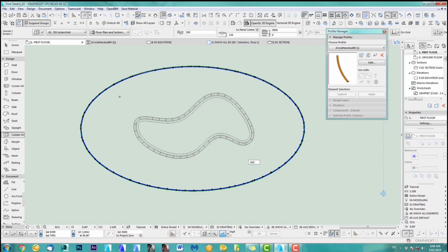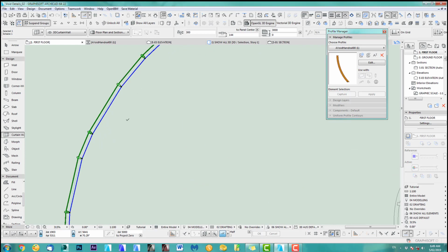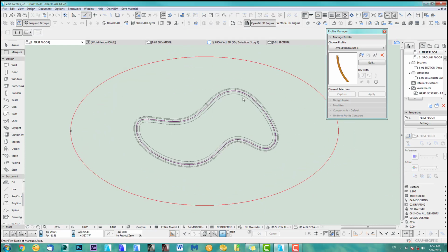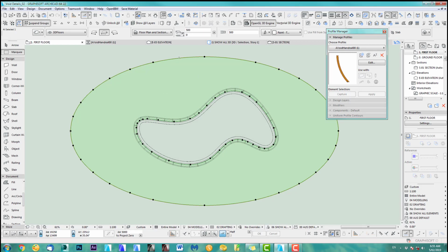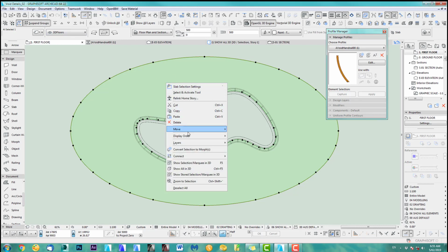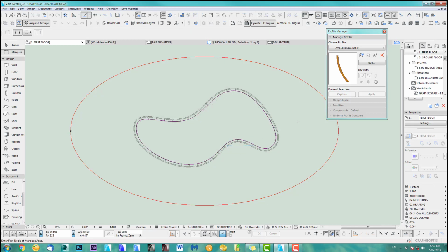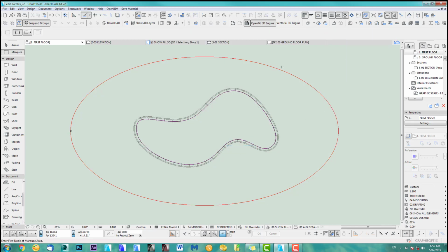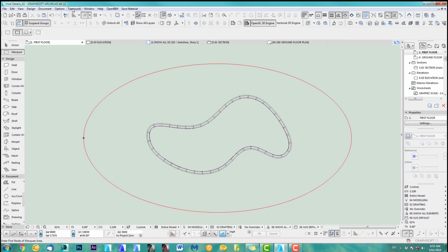they better be 2 meters now. Oh, I know why. It picked the slab polygons. You see here. So I gotta turn that layer off if it doesn't do it. So which is layers, hide layers, and actually I can get rid of this one. So let's just try again.